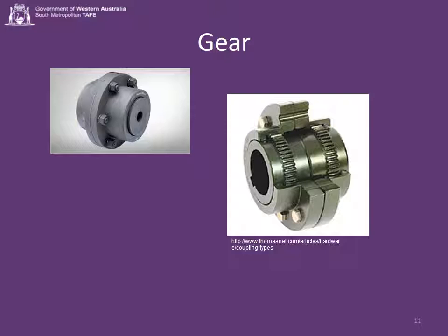The heavy-duty design is still flexible. It counters all types of misalignment, axial, parallel and angular, and has large axial movement capacity. They're suitable for high-temperature environments up to 120 degrees Celsius. Specially designed crown teeth can reduce backlash and radial clearance.